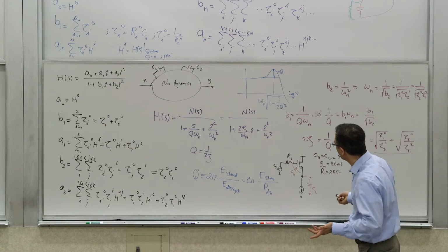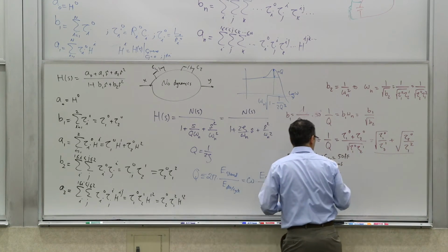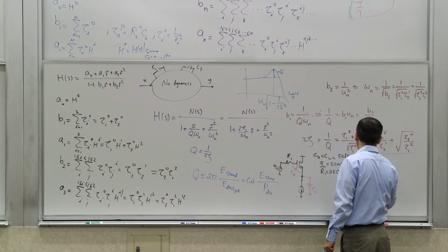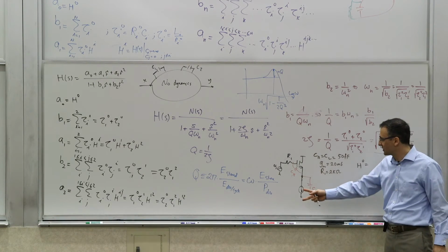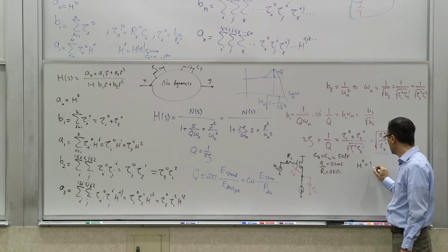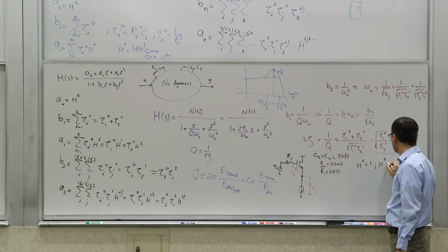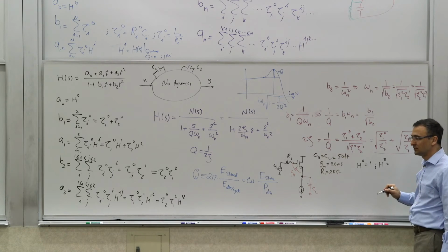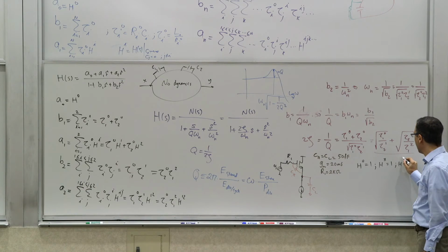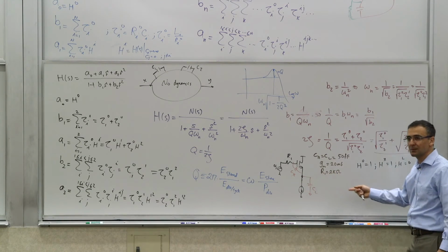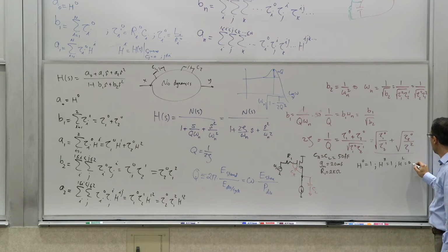The time constants are trivial here, so let's do it very quickly. H0 is going to be 1, because this resistance is infinity. H pi is still 1. HL is 0, because if you short circuit this, nothing is at the output. And H pi L is also 0, since both of them are short circuited. So those are the transfer constants.